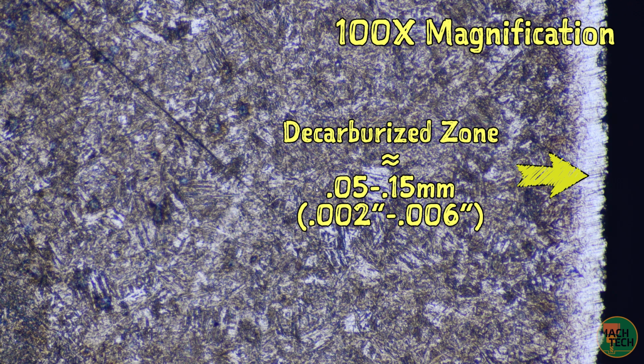When we were carburizing the steel, the low-carbon steel was in a high-carbon atmosphere, so the carbon tended to migrate from a zone of high concentration to a zone of low concentration, meaning the carbon diffused into the part. However, when we heated the part prior to quenching it to harden it, we had a high-carbon part in a low-carbon atmosphere, so the carbon tended to leach back out of the part.